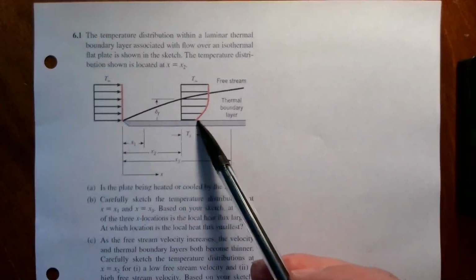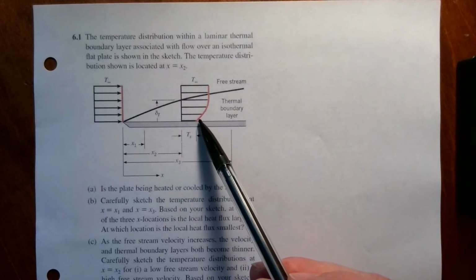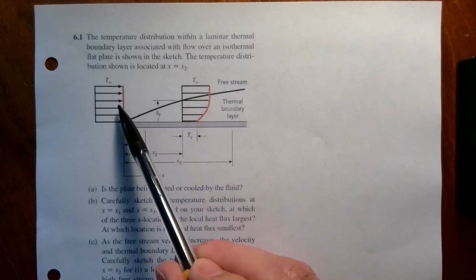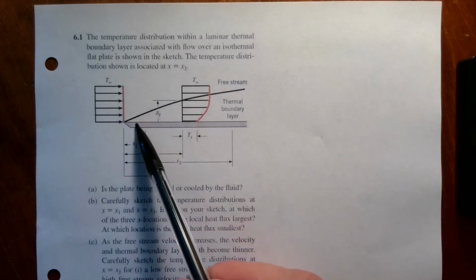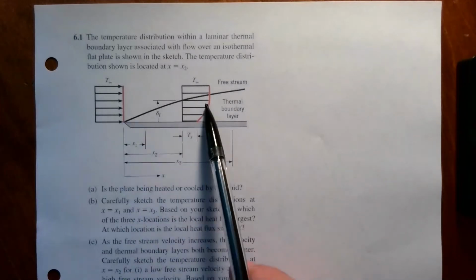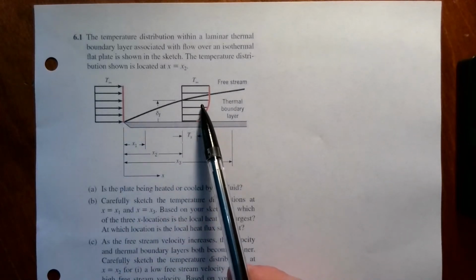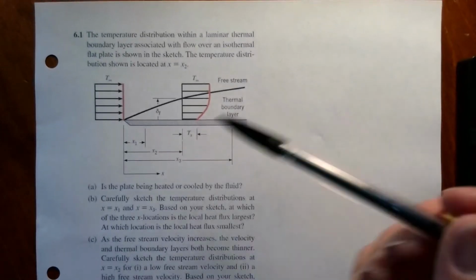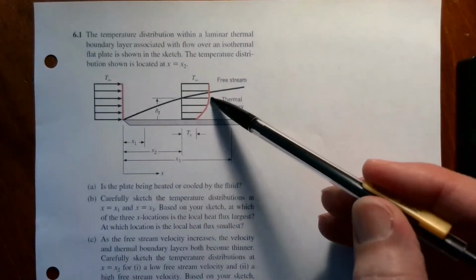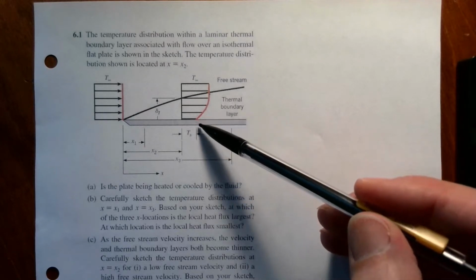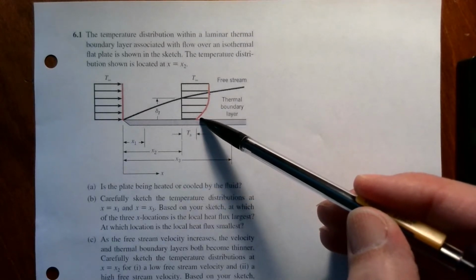So they've drawn a boundary layer situation. This is the thermal field because you see these are temperature profiles here and here. So there's a uniform temperature profile before the effect of the plate is here, right? As the fluid is now passing by, a temperature profile farther down here, right, is now going to have to vary between T ambient down to the temperature of the surface.